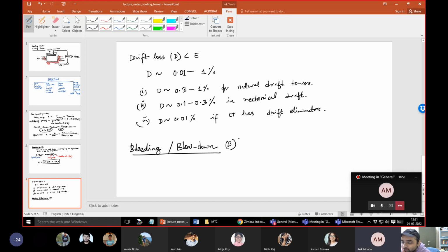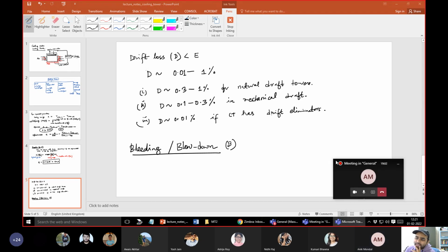So the cooling tower won't work if that happens. It stops working. It's not that way. See, the issue with the dissolved solids is that they scale and ultimately they foul the surface of the heat transfer equipment or mass transfer equipment, right? That is the problem with dissolved solids, with long periods of use or even in the short term.